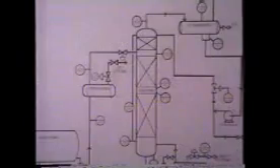If this happens, the top of the column will not be kept cool enough to prevent the bottoms product from vaporizing and contaminating the overhead product. Finally, there might be an electrical failure in the system. Although there are a few extra steps taken, the emergency shutdown procedure is similar in purpose to the short-term shutdown. That is, the system is expected to return to operation once the emergency has been dealt with.